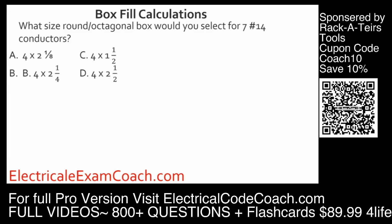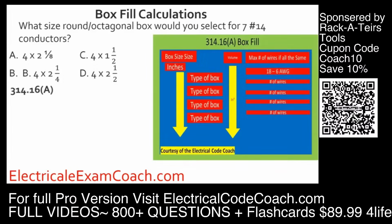What size round octagonal box would you select for 7 14 gauge conductors? We're going to head to table 314.16(A). We're going to start here on the right hand side and find our gauge wire. Then we're going to come down and find a box that fits it and be sure when we cross over that we stay in the right category of box, and we're going to select C.